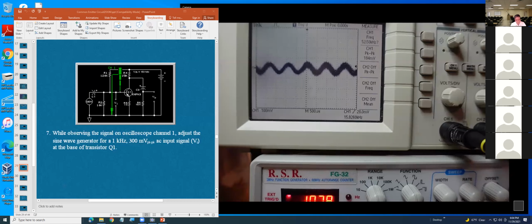Try going average to allow the processor of the oscilloscope to condense the signal? No, cannot. Use the cursor to measure. Exactly. In this case, you don't use automatic measure anymore. You must use the cursor. The signal is too noisy, so the scope measurement will be wrong.